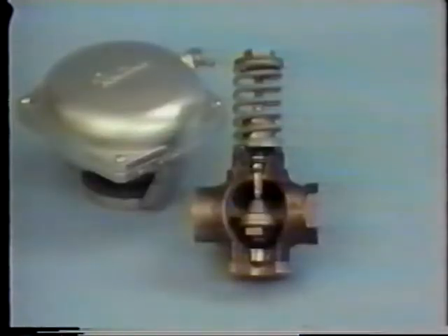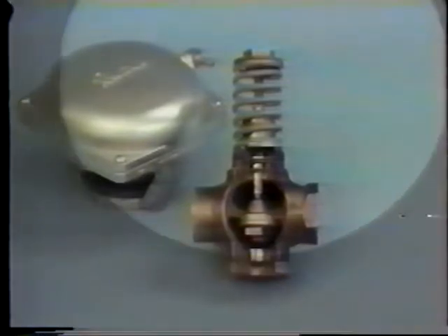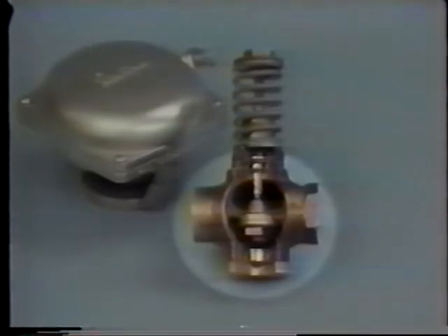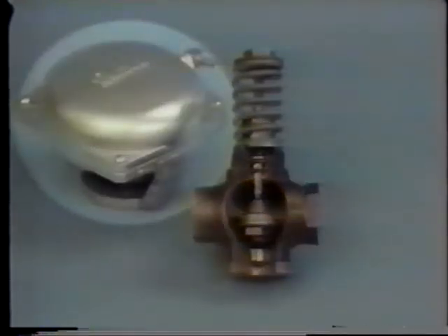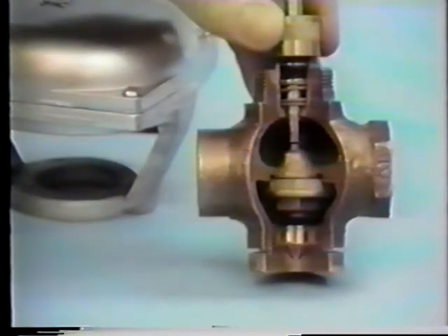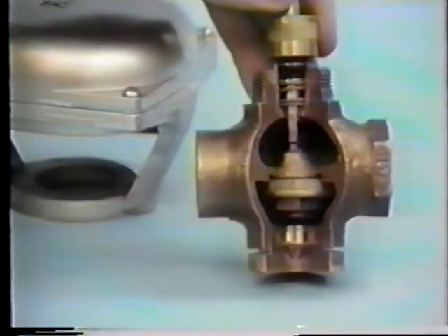This is a normally closed valve body assembly. The spring pushes up against the spring adjusting nut, pulling the plug assembly up against the valve seat. This valve body utilizes the same actuator as the normally open valve. The packing assembly in the normally closed valve is identical to the normally open valve. Note that the valve body is of a different casting than the normally open valve.